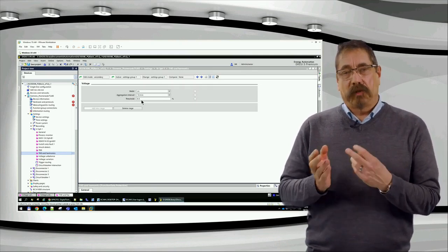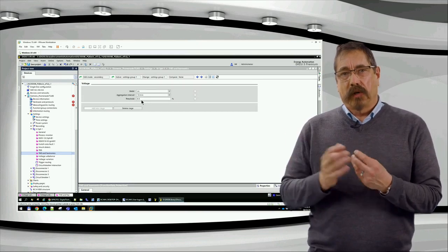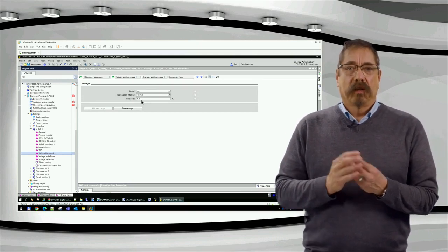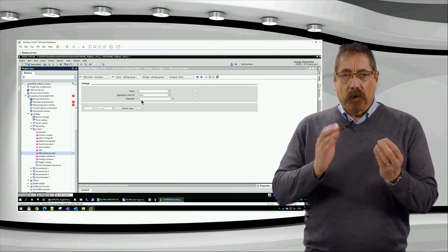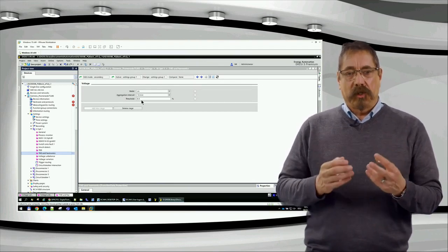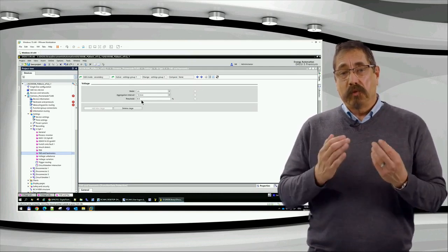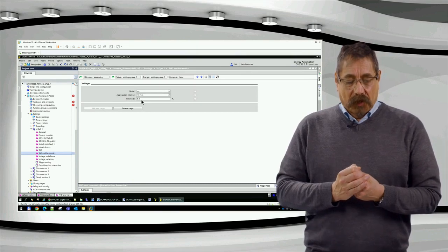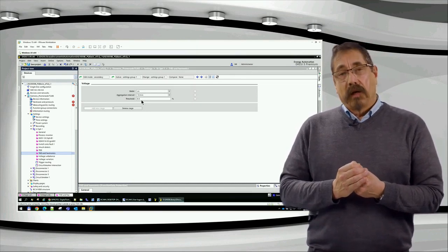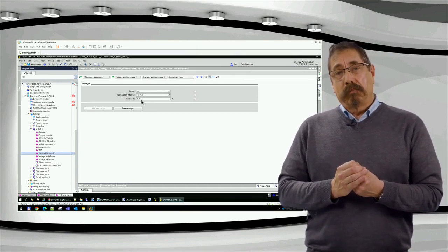This is a difference compared with the power quality recorders. They are doing the THD up to harmonic number 40. But we can also give a statement here if the total harmonic distortion, this means the harmonic voltage level, is too high, when from the second to the 20th harmonic the threshold increases above 8%.